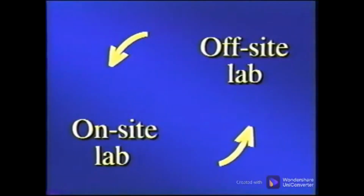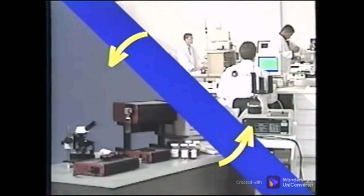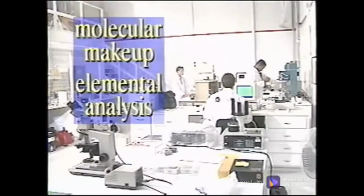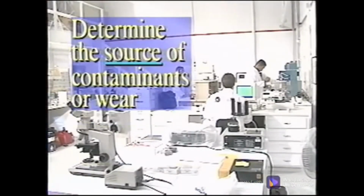An off-site oil analysis lab designed especially for handling industrial oil samples, such as CSI's tribology lab, has the equipment and expertise necessary to provide detailed analysis of your lubricants to help you maximize the life of your machines. In your on-site lab, you can detect particles in the oil, but here we can provide the exact molecular makeup and elemental analysis which can help you determine the source of the contaminants or wear.